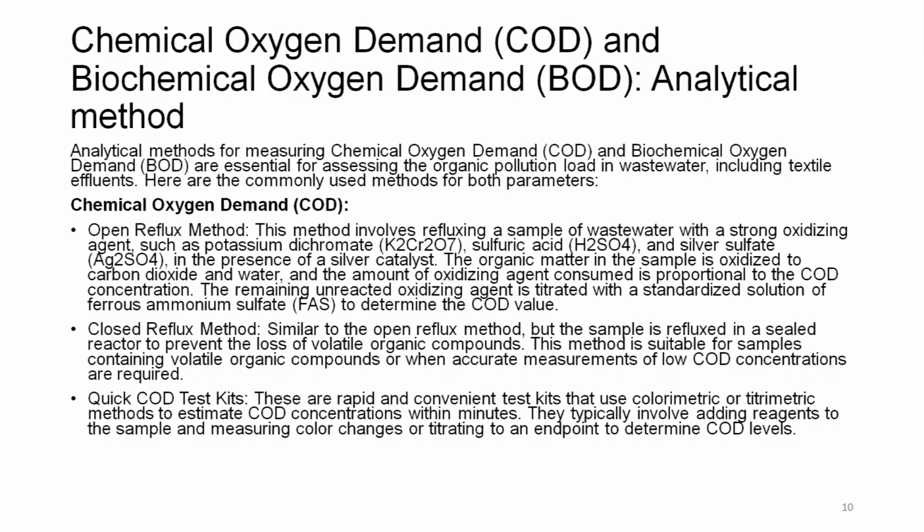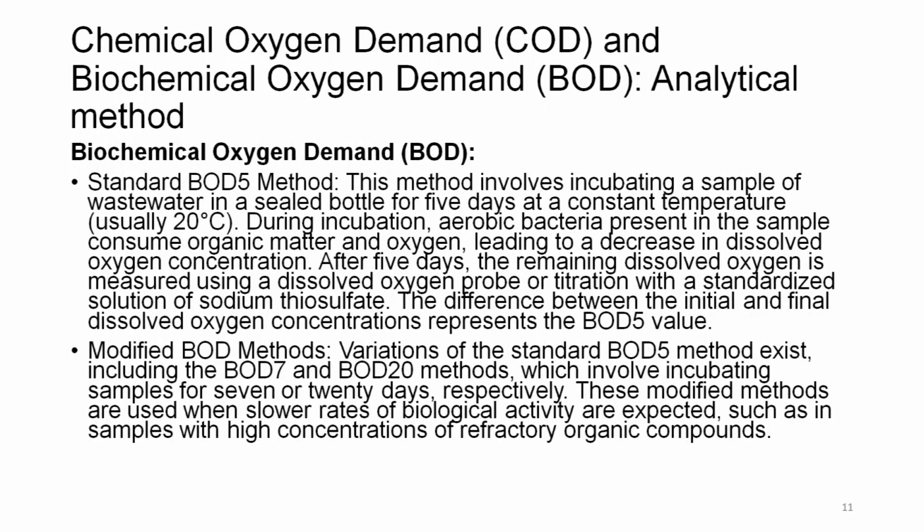Quick COD test kit. There are rapid and convenient test kits that use colorimetric or titrimetric methods to estimate COD concentrations within minutes on the site. They typically involve adding reagent to the sample and measuring color changes or titrating to an endpoint to determine the COD levels.